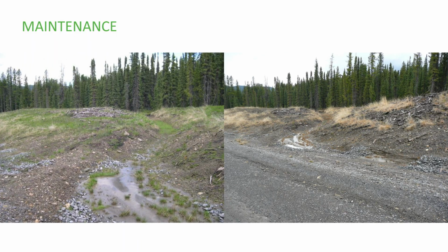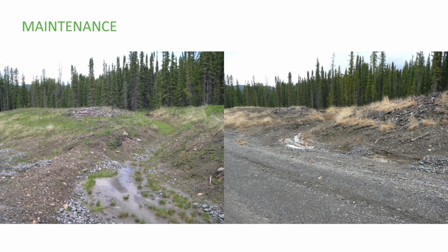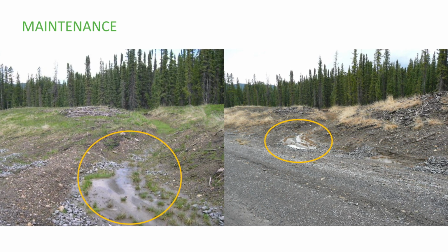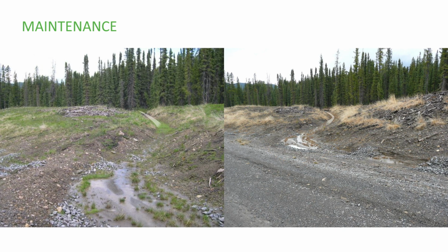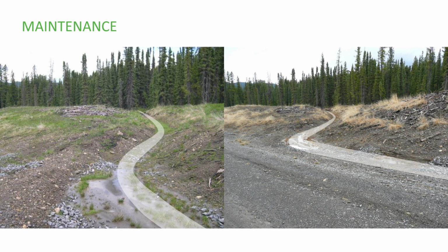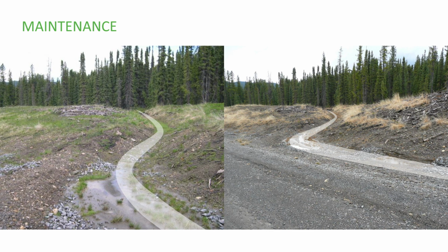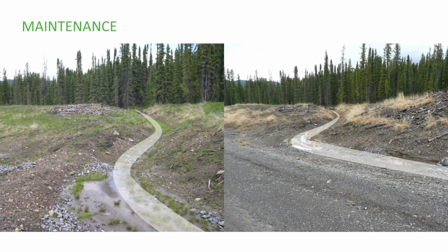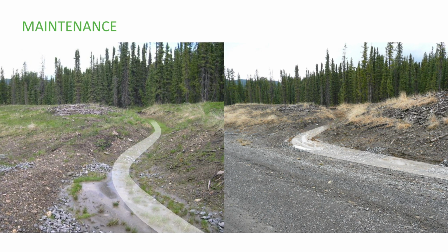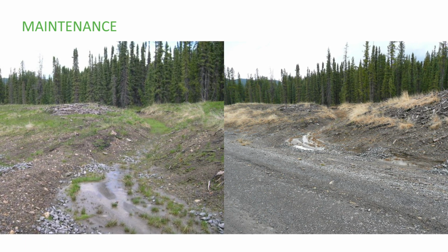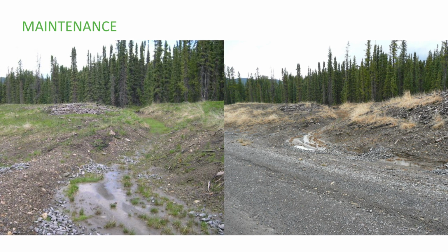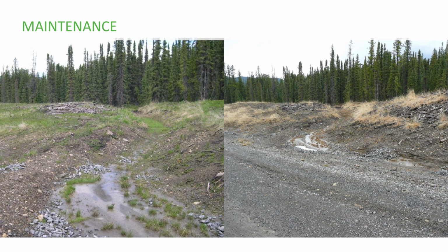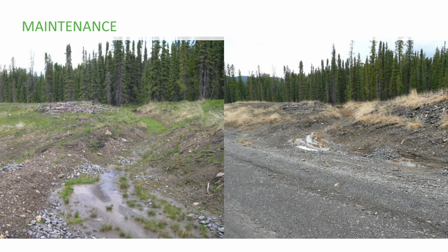Ditch offtakes may show signs of hindered flow and sediment buildup. This offtake shows sediment buildup over time, as highlighted by the yellow circle. The initial turn of this offtake is likely not gradual enough and may have too flat of a gradient. Water doesn't flow uphill, and shallow grades can be difficult to discern with the naked eye. Use basic survey tools, such as a clinometer, to ensure adequate drainage. Additional earthworks may be needed to establish a slightly greater gradient.